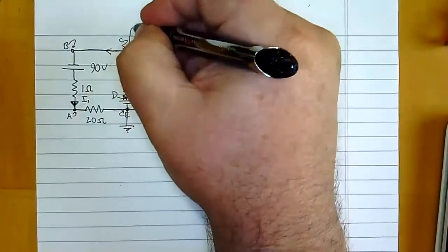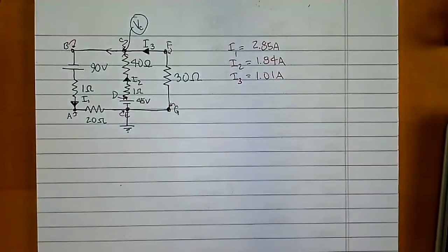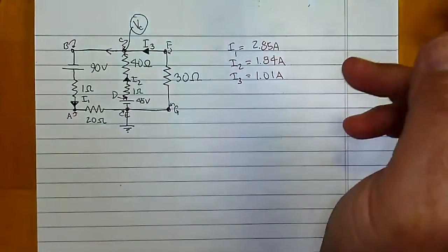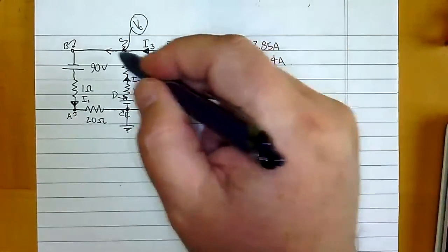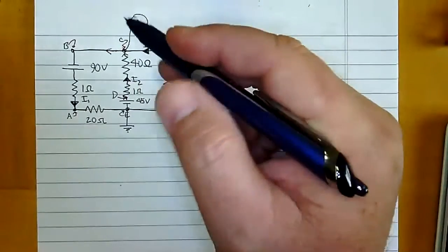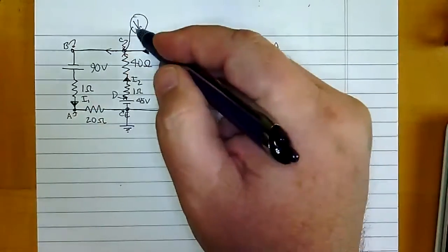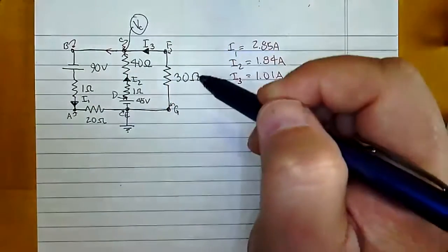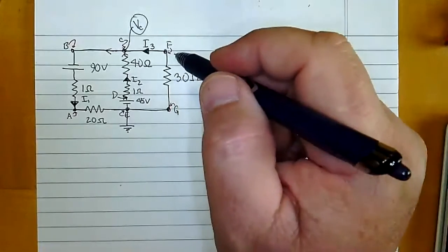That means this voltage right here is what I'm going to call VC. So that's the voltage at the top. We have no idea what it is. It could be positive, it could be negative, it doesn't matter. But the big thing is we're going to get an equation for each of these nodes, one here, one here, one here, that'll have two variables: VC and the current I1 in this node, VC and the current I2 in this node, and VC and the current I3 in this node. So by doing that, you can actually solve for the individual currents.